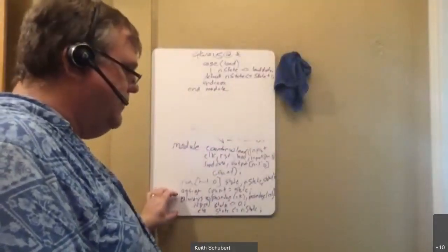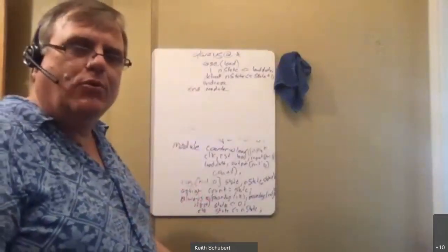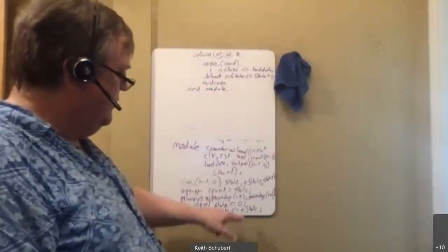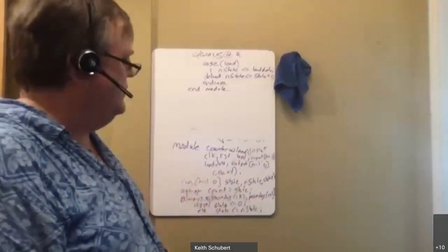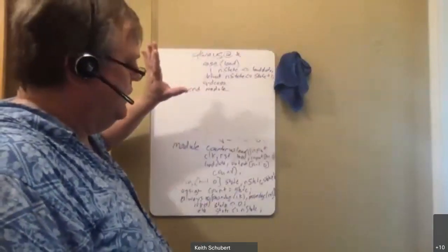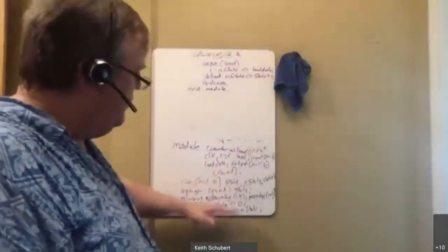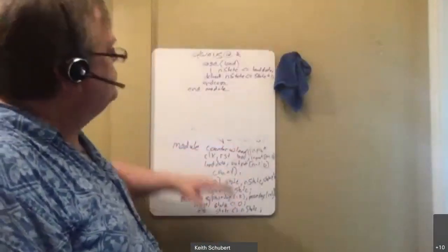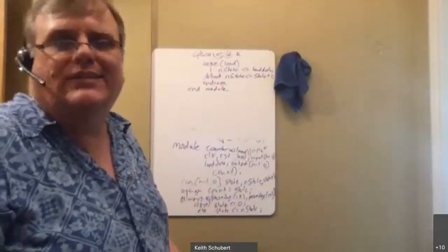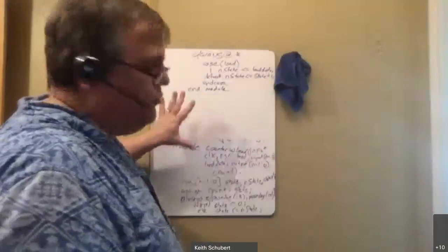I really like making very safe registers and then doing safe next state logic. That separation, while you don't have to, you can technically build them into it. I could make a complicated statement here that replaces next state, but it's not as pretty. You don't see it as well. It's harder to get the logic because everything becomes a special one-off. If you get very used to just building the registers and then doing the next state logic as a separate unit, you'll just tend to get fewer errors. And that's always a good thing. So this would build my counter. Do we feel good with this?